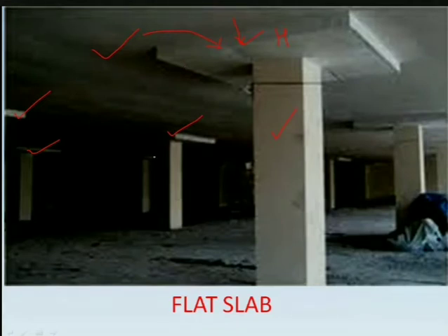important, because if you are say in a theater and the span will be very much big in a theater, and you are sitting, imagine this is a theater room, and if you are sitting and watching a movie, and if beams are there here connecting the columns, your vision will be blocked. Okay, you will not be able to see the screen very properly. So in such cases, in case of commercial structures, what you do, you go for flat slabs.